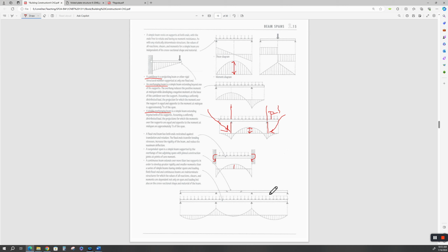All right. Multiple spans work the same way. Multiple fixed point spans. Okay. So we have fixed beams, suspended beam, and continuous beams over more than two supports. Now this is all one long beam. This is not like a bridge where at each one of these columns is an expansion joint. Those are all simple spans. But this would be like one long fixed beam, okay?